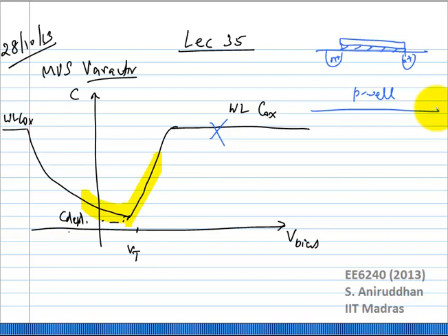But you want to completely prevent it from happening. And by the way, unfortunately the problem is this: in a normal NMOS, this is actually the P substrate. You can't randomly change the doping of the substrate. If it's a well, you can, okay, but not the substrate. Any other ways you can prevent it from inverting?